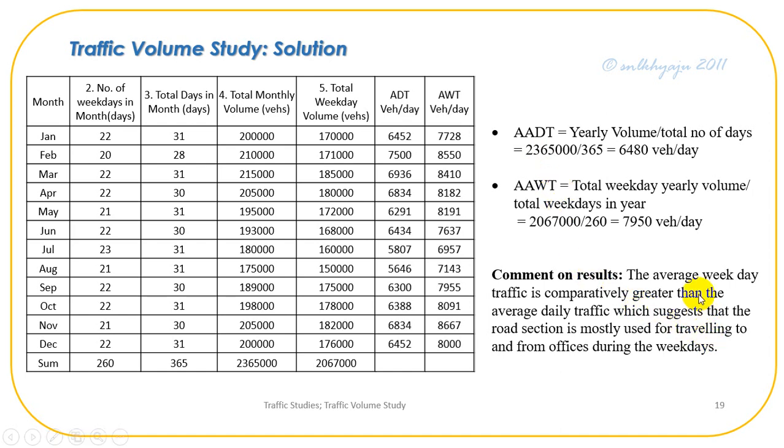the average weekday traffic is comparatively greater than the average daily traffic, which suggests that the road section is mostly used for traveling to and from offices during the weekdays.